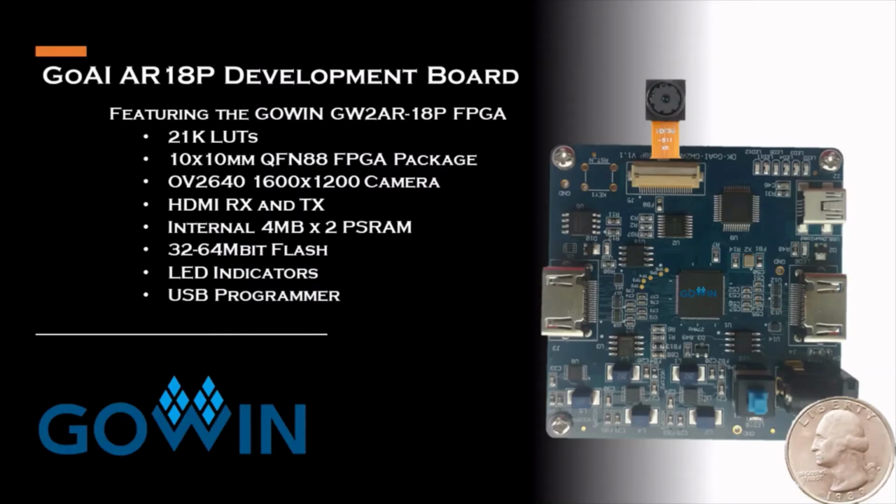The next board we have is the Gowin AI GW2AR18P development board. This board has significantly more FPGA lookup tables, 21K lookup tables in total. It's in a 10mm by 10mm QFN package. Other packages are available, but this is the one on this particular development board. Same situation with the cameras. OmniVision 2640 comes with the board, but there's other options as well that are compatible with the same connector.